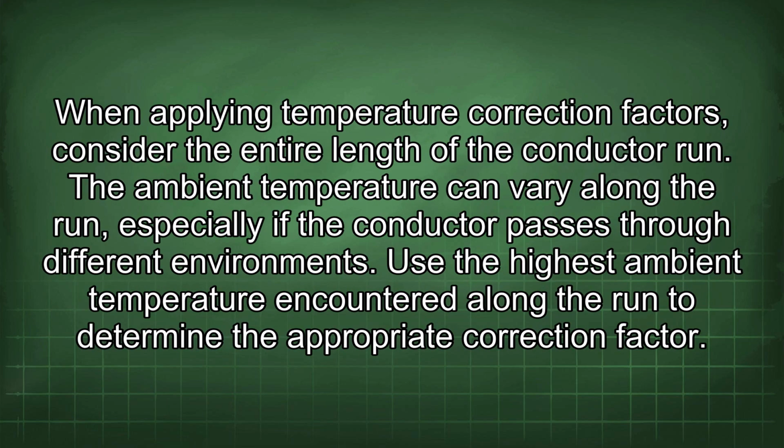When applying temperature correction factors, consider the entire length of the conductor run. The ambient temperature can vary along the run, especially if the conductor passes through different environments. Use the highest ambient temperature encountered along the run to determine the appropriate correction factor.